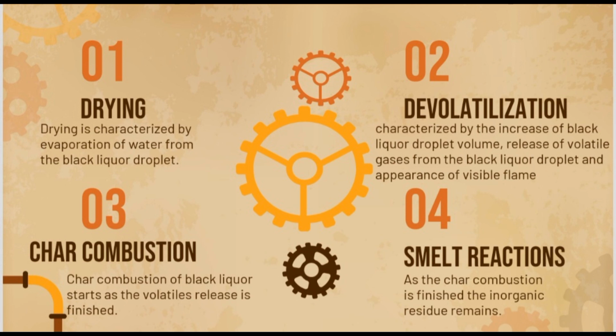The first is drying. Drying is characterized by evaporation of water from the black liquor droplet. It is often experimentally defined by the absence of combustion, a visible flame. Evaporation of water requires heat. Drying of a black liquor droplet proceeds as fast as the heat is transferred to the droplet. Even in the furnace, drying is limited by the heat flux to the droplet.